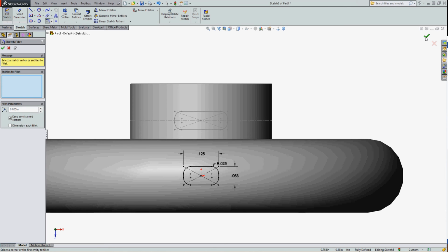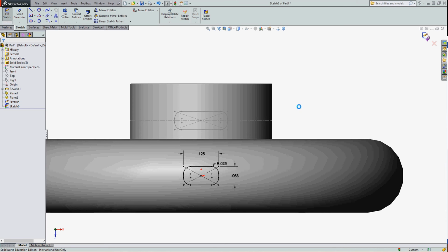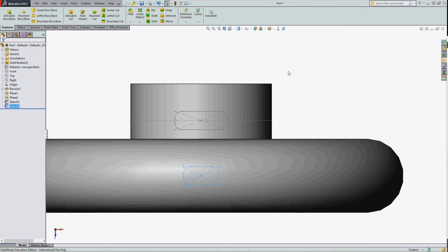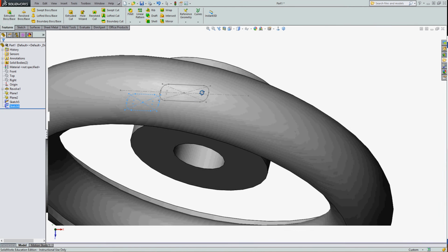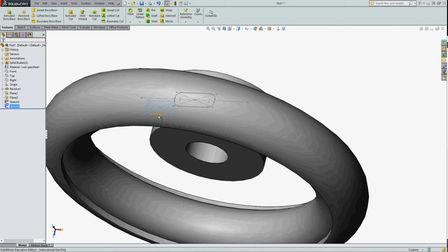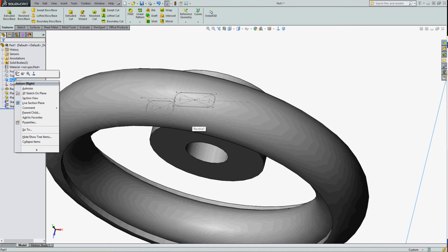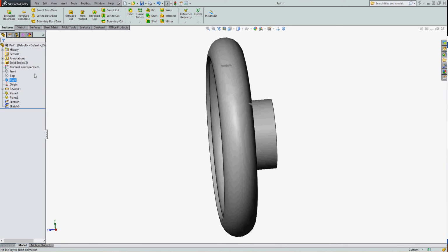I have two similar shapes to create my loft profile from one to the other. If I go ahead and create the loft using these two sketches, it will just join this profile to this profile with straight lines. So I want to add another sketch in my right plane telling the loft the center line path to follow.